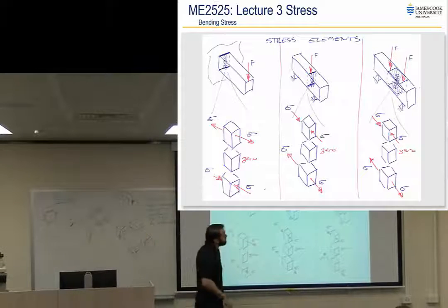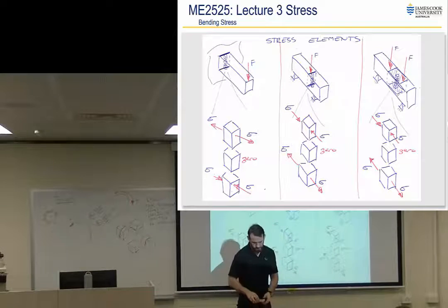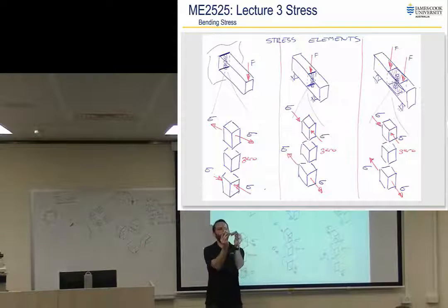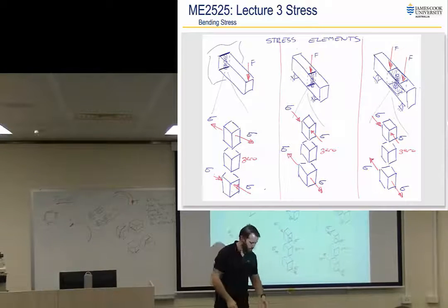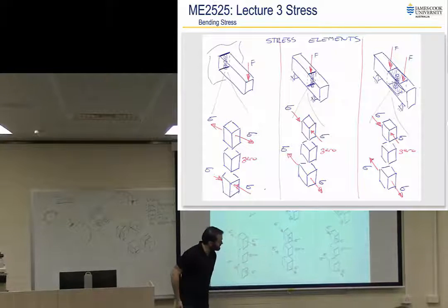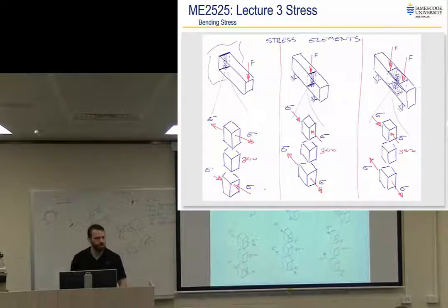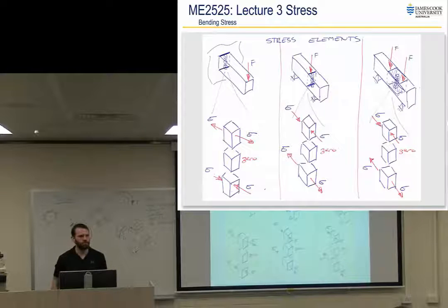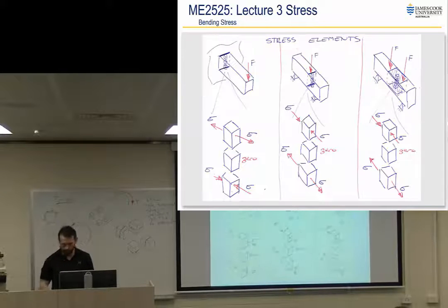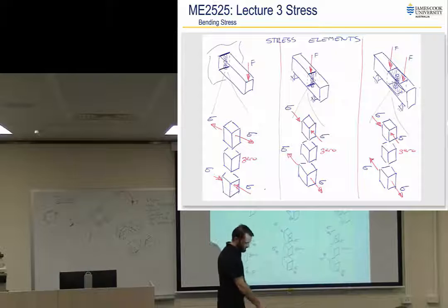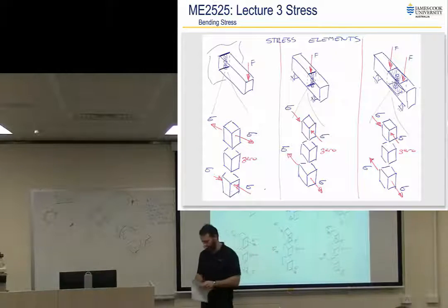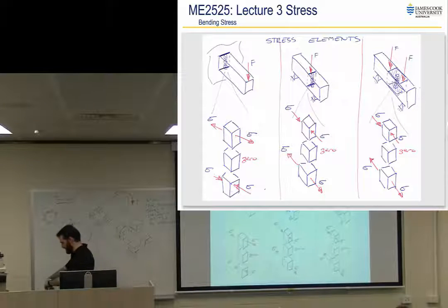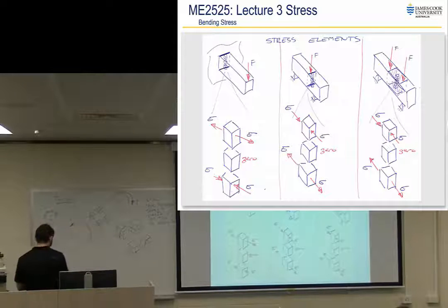And once again, forces up at the sides, forces down, so we can visualize that that's going to be bending down, so we've got tension on the bottom and compression on the top. And that's what I've drawn right there. Okay? Is everyone comfortable with those? Good. What do I got next? Transverse shear. All right, let's have a problem. We can do this problem and then you guys can have a 5-minute break and we'll get through transverse shear after that.